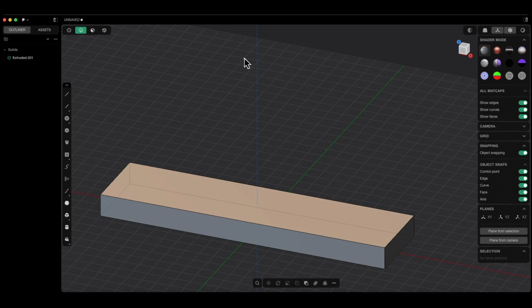We will draw another rectangle. Choose to draw the centered rectangle. Now I want the center of the rectangle to be here on the top face of this solid, aligned with the z-axis, and when this snap is active, I click the left mouse button and now the rectangle's center is here. Next, I want one corner of the rectangle to lie on the solid's edge. I hover the cursor over that edge and notice that one dimension of the rectangle is 50 millimeters.